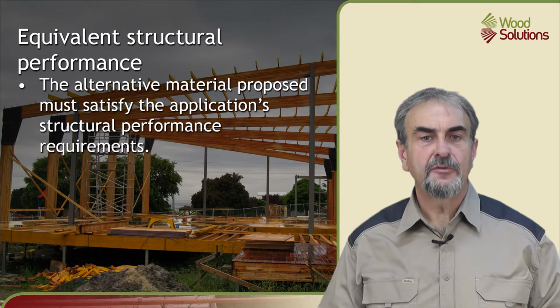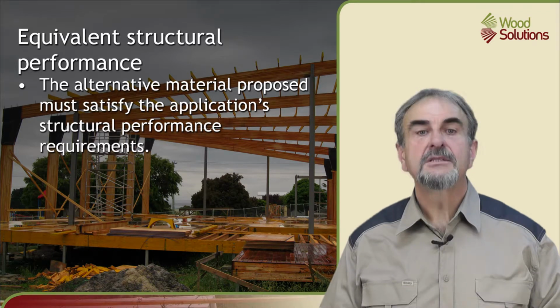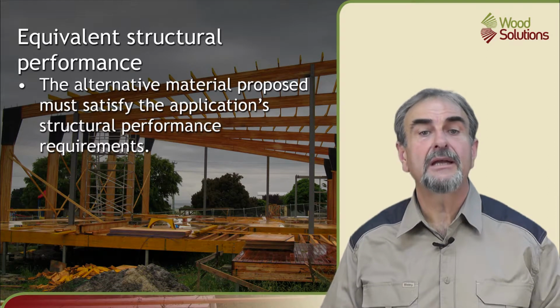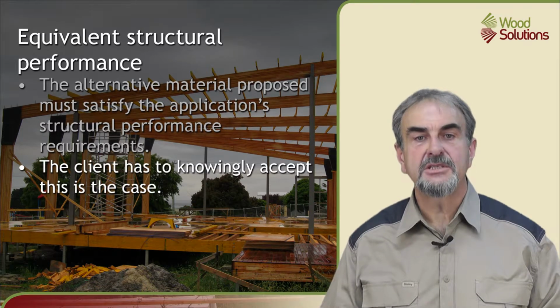This means it has to perform the same job in the same application with the same design loading. So if the ordered material was to be used as a floor joist spanning 2 metres at 450 centres in a conventional house, the alternative product has to be able to do at least the same. Then the client has to knowingly accept this is the case. Proposing this type of alternative product requires care.